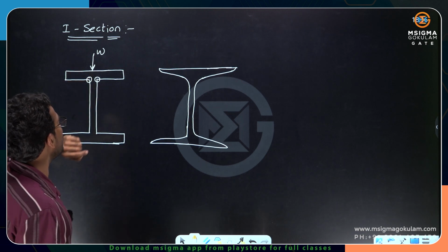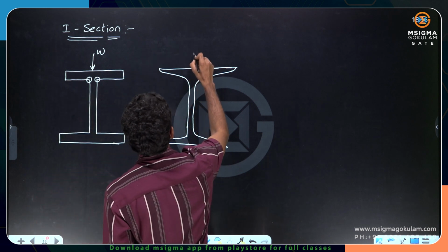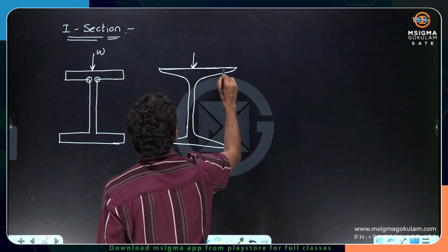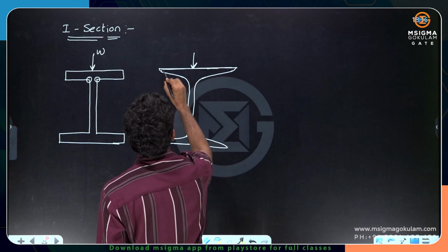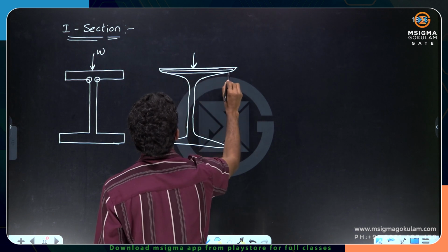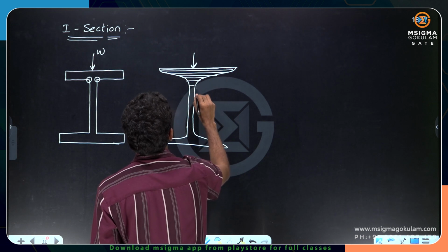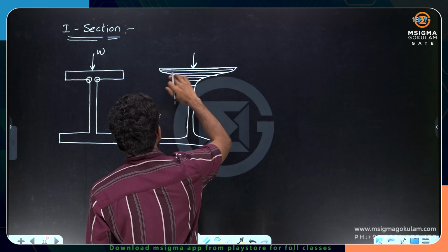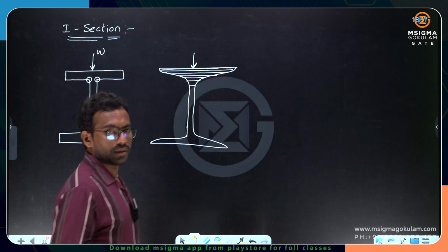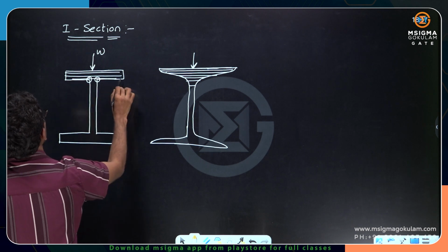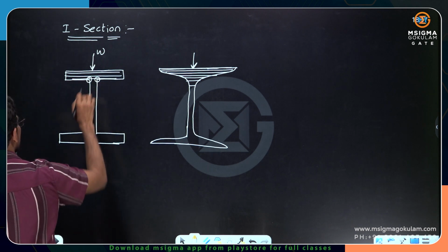That is why, practically, the stress concentration is eliminated by gradually reducing the dimensions. Here the dimension is more, and as you go down the dimension keeps on decreasing. This is how the dimension gets decreased, and then the stress concentration effect is eliminated. But here the width is uniform and suddenly it is reduced, that is why stress concentration comes here.